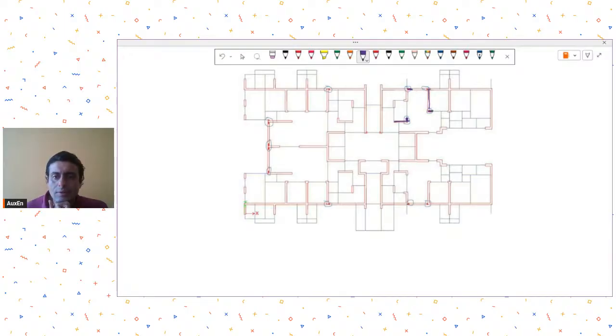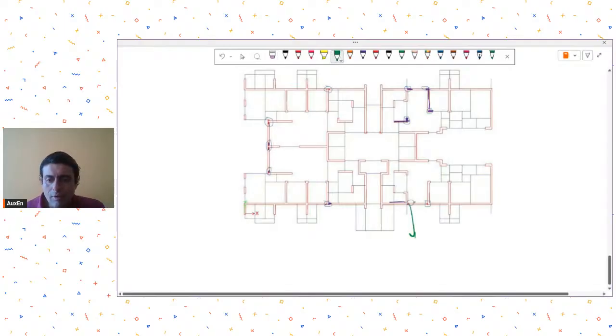This seems to be failing according to him. This is failing. This is failing. These nibs are failing. I'm not sure how you could find out in this. I mean, this is the complete wall that you have given. In this case, how could you find out that this corner is failing? I'm not sure, because ETABS will not give you whether the corner is failing or not.